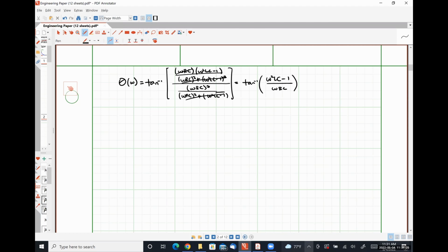All right. So this was a band pass filter. Okay. So when we have that series RLC combination, if we take the voltage drop over the resistor, we see a band pass filter response. So now let's do the opposite.